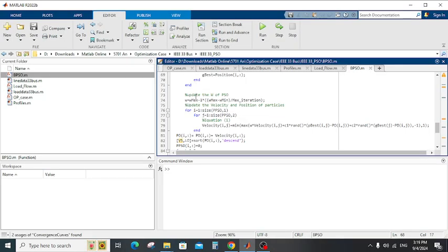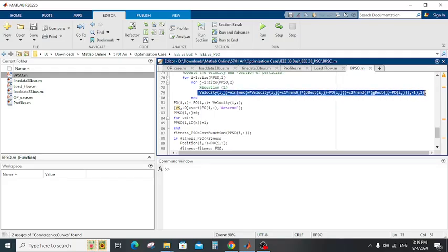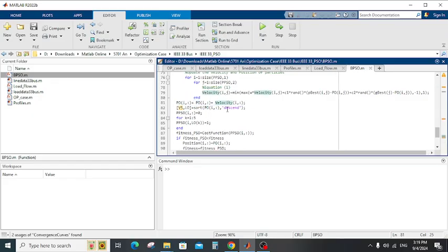And after that we updated the weight of the PSO and updated the velocity and the position of the particles depending on the equation of the particle swarm optimization. This is the equation for updating the velocity, and after we updated the velocity, we updated the new position depending on the new velocities. After we updated that, we sorted the position, and then we selected which lines have the biggest values and set them as open depending on the line values.